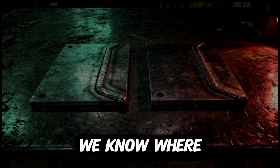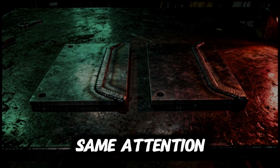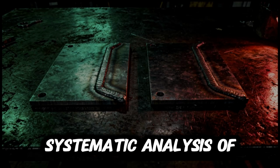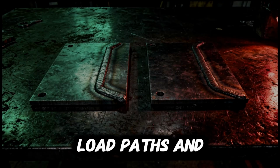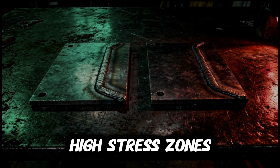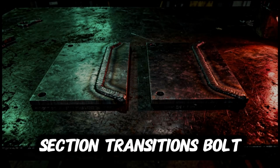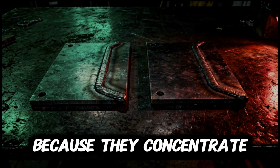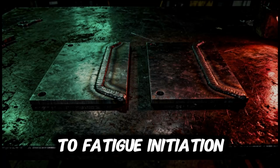And how do we know where to look? Not every square millimeter gets the same attention. Identifying critical inspection points requires systematic analysis of component geometry, load paths, and surface exposure. High-stress zones such as weld toes, section transitions, bolt holes, and support interfaces are prioritized because they concentrate mechanical loads and are prone to fatigue initiation.